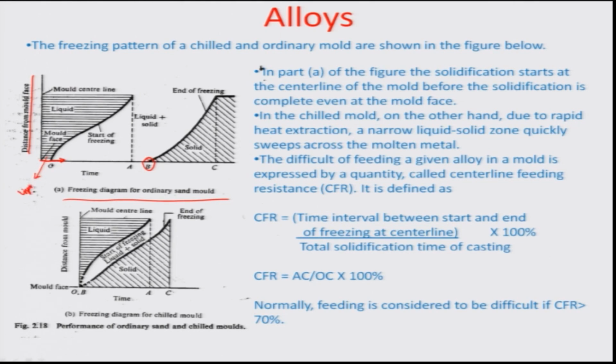This is the liquid part. This part here is the liquid plus solid part. So, therefore, there is a partial solidification, partial liquefaction, and then finally the whole mixture freezes here to the complete solid state, as you can see here at the point B. So, between this O and B, the available phase is a mixture of the liquid and the solid, and beyond B there is a complete freezing. So, therefore, all this portion right here is the solid portion of the mold.